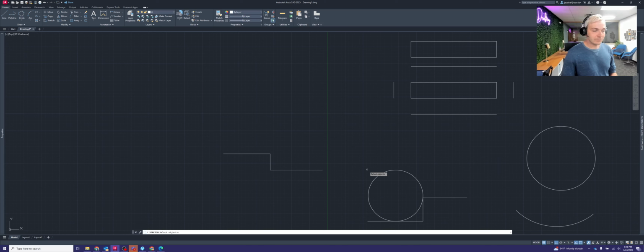In order to do that, you are going to take your cursor. I'm in the stretch command right now, and I'm going to start by clicking in the blank space to the bottom right side of what I'm trying to stretch. So right there. Go ahead and unclick and move your mouse up to the top left of the area that you're trying to stretch or increase in width.